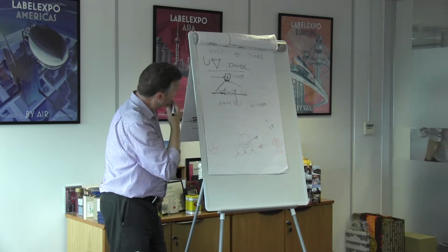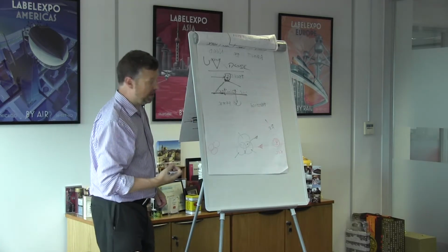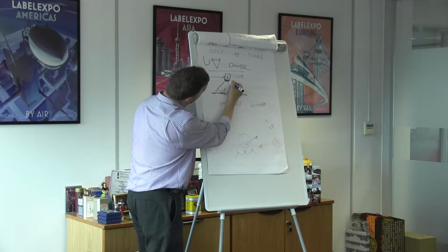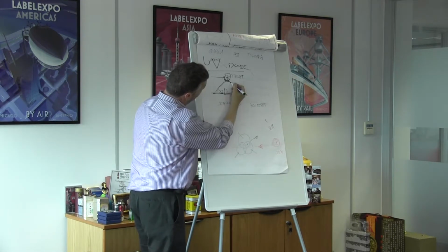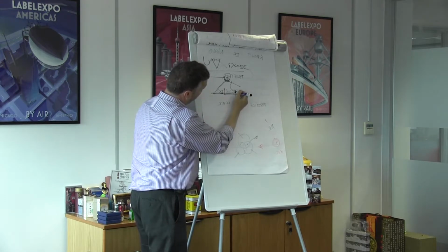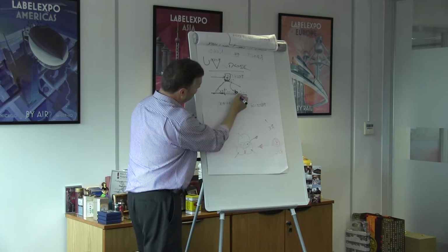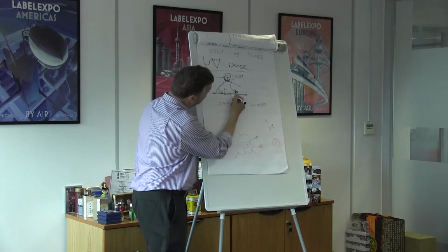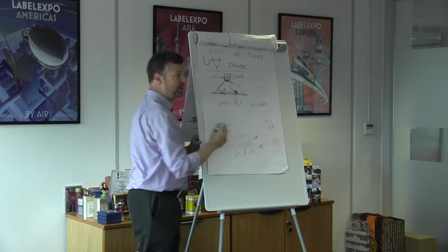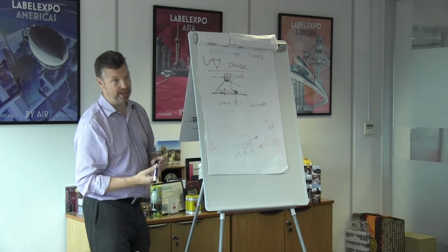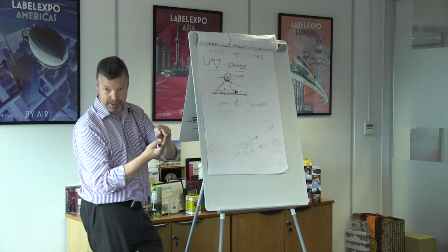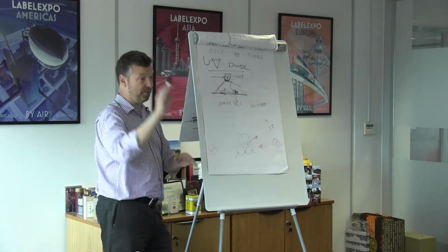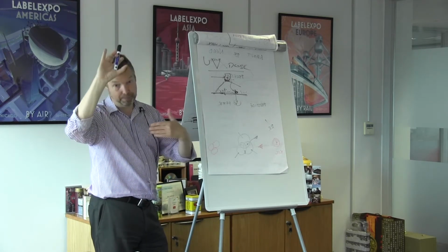So what GW are going to do, and Federico has been pushing this, and you'll see this on his M6 press at Label Expo, is that rather than having the sensor up in the lamp, they've moved it so it sits just above the web in front of the lamp. It's not actually on the surface, but about a couple of inches off the surface of the web. So it's measuring the amount of energy that hits that part of the web, and it can then ask Flint or Sun Chemical how much power is needed at this web speed to cure this ink on this material. They know exactly what that figure should be, so they just have a little monitor that says yes or no, has enough power reached the web.